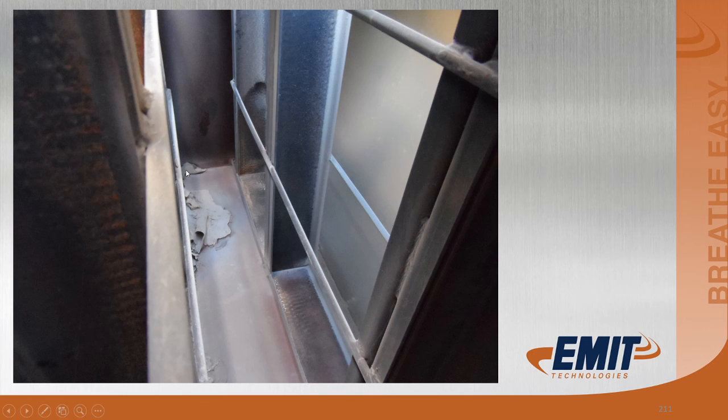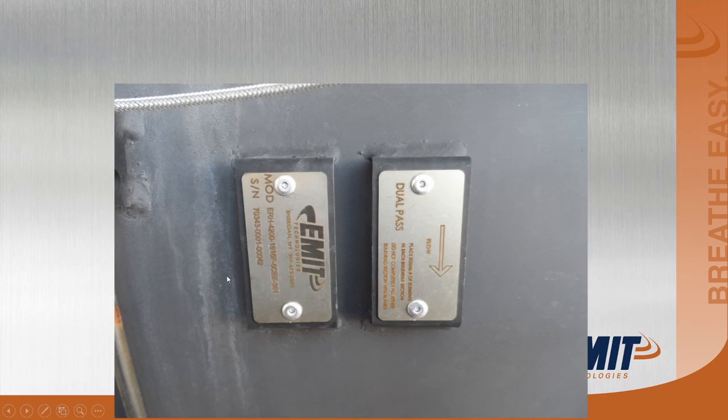This is something you do want to look out for, though. When you're dropping catalyst elements in, make sure you get all the old gasket material or debris out of the channels, because that catalyst element is going to go down and sit, and if it doesn't seal tight, you're not going to get great numbers. You're going to get some gases bypassing the element.